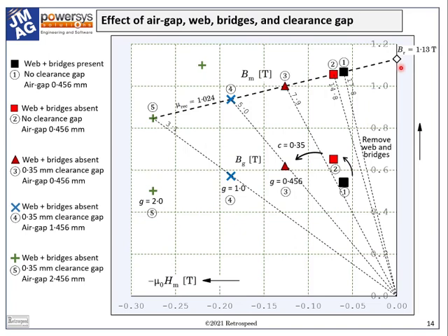And of course it would be perfectly safe in there, but also perfectly useless. There's also another set of markers lower down, and these represent the average flux density around the air gap, so they give an idea of the generated EMF. For case 1 we have 0.543 Tesla. Now let's consider the interesting step from case 1 to case 2.